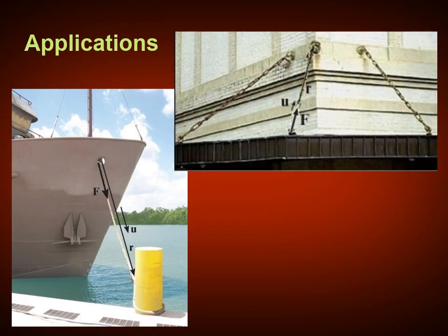You can also use this, for instance, if you look at this awning, you have three chains holding up the awning. And so knowing where those chains intersect is one application. And you need to do this because that's how you ensure your structural stability. So each chain is going to contribute to holding that awning in place, but you want to make sure that the load is evenly distributed, because if you overload a single chain, you could lead to failure under wind or rain or other loading events.